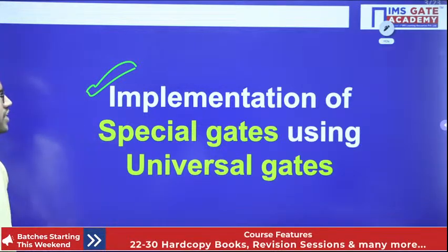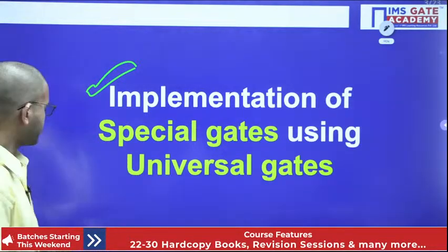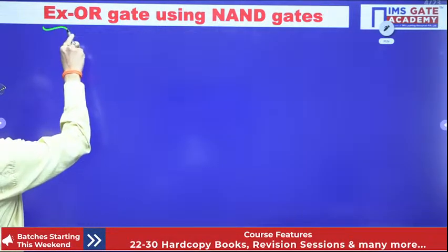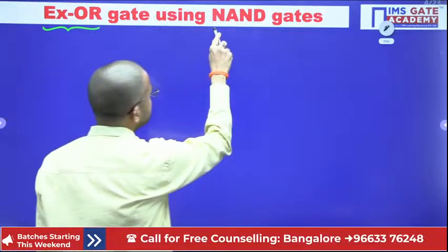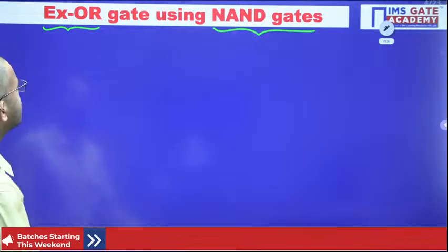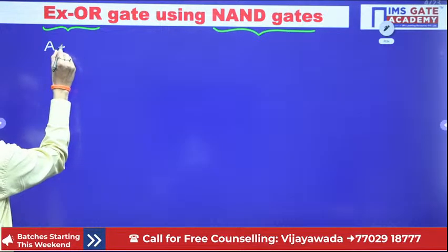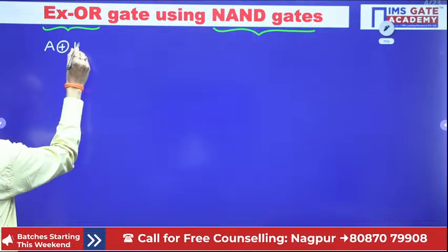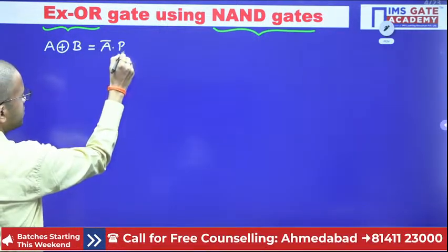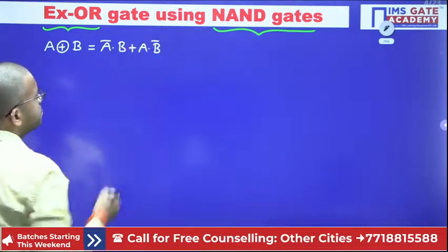So all of you put the heading: implementation of special gates using universal gates. Right. First let us implement exclusive OR gate by using NAND gates. First of all, write the A XOR B expression. A XOR B is nothing but A bar B plus A B bar.